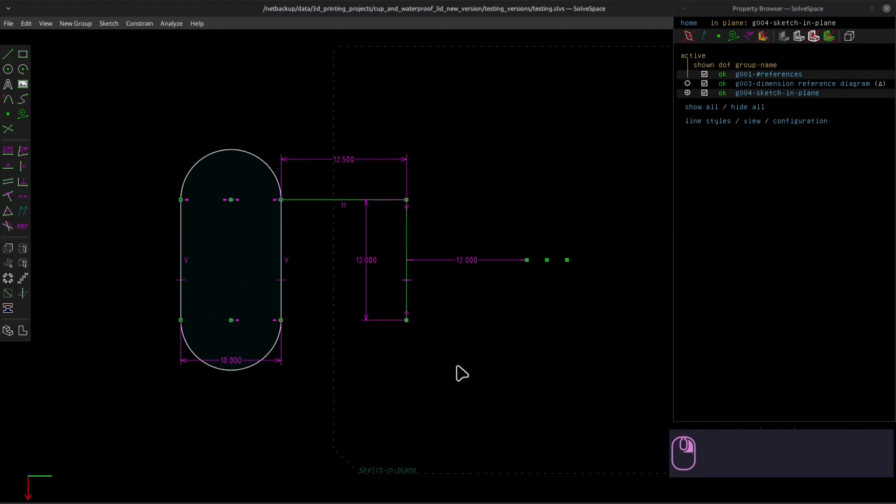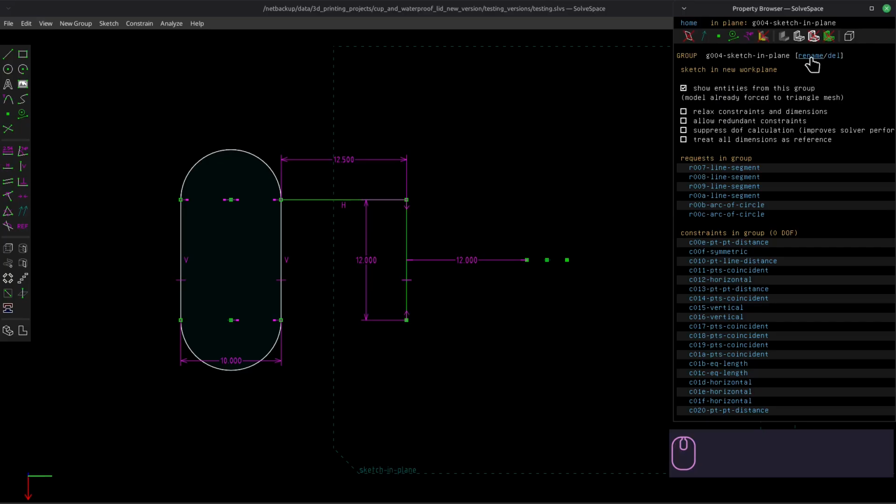Let's look closely at these dimensions. The center to center distance is the same as the construction line that defines things here. And it's 12.5 millimeters away. I'll explain why later. And it's 12 millimeters distant from the outer edge of the cup. This point here is the outer wall of the cup. This is the inner wall of the cup. And this is a reference line that I'll be using later on. I'll explain later why that's there. Okay, so that takes care of this drawing. And I need to give it a name. I think I'll call it Handle Top Sketch.